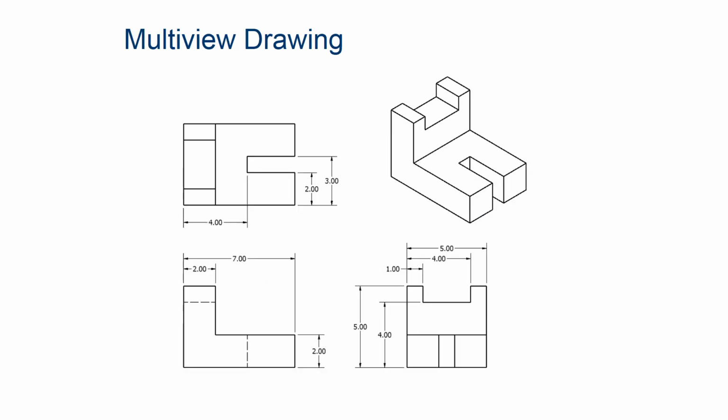So here's another example. This time it has dimensions. Once again, we have the isometric view that's been placed into the item, and that will show us that we have selected this face as giving us the most detail. So that's why we've gone down here and put that in the front view. So the front view gives us the most detail about the object, shows us the most about its shape, and has the fewest number of hidden lines.